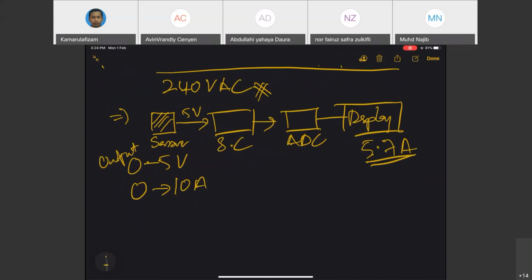All right, now you should go to find the signal conditioner in this case, because we have sensor running output maximum 5 volts, so you should basically consider the whole thing running at 5 volts. All right. So I'm putting some assumption here that the signal conditioning is running 5 volt. I'm putting also ADC to run at 5 volt. Of course, my display system is also running at 5 volts.